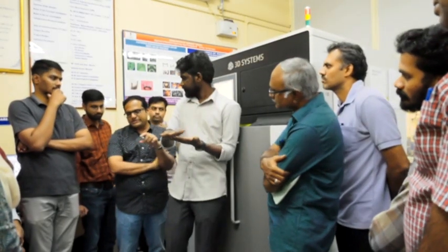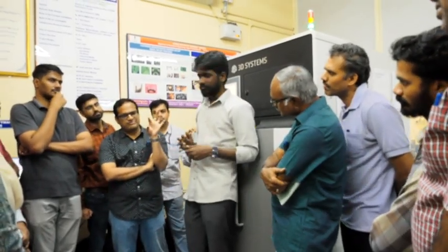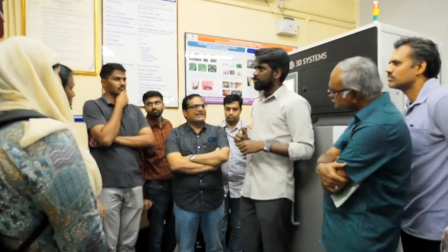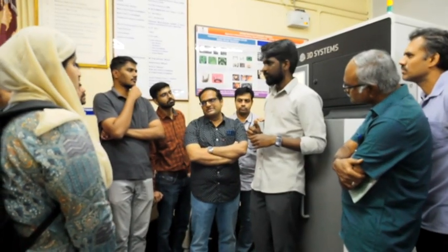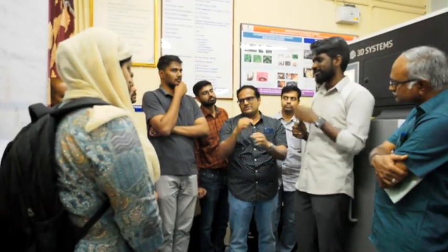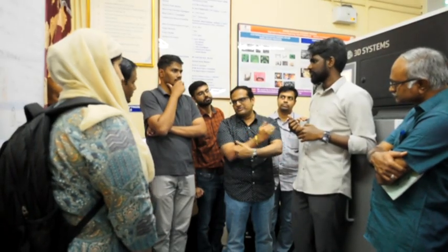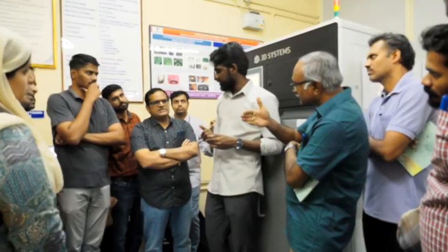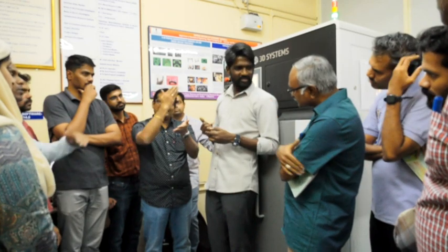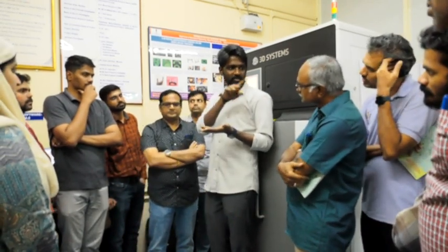Layer thickness is nothing but the Z movement of the build platform. Yes, that thickness we can vary also. We can vary it, but right now we have fixed it. All layers have uniform thickness, and you cannot vary it in between. From the first layer to the last layer it is fixed, whether it is 100 microns or maybe 50 microns, but you have a range. Can you change the powder also? Yes, obviously. Can you build curved parts? Yes, curved means you build it through a number of layers. Stacking 2D layers gives the 3D component.